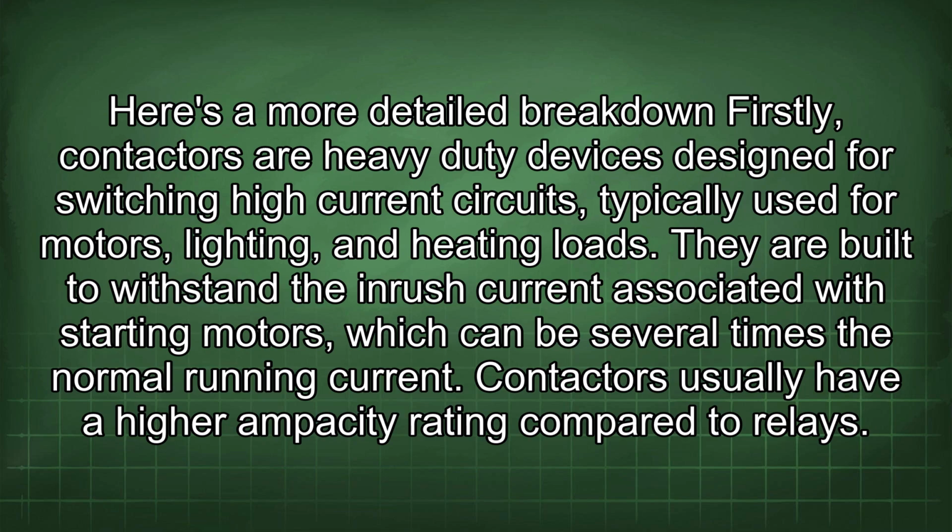Firstly, contactors are heavy-duty devices designed for switching high current circuits, typically used for motors, lighting, and heating loads. They are built to withstand the inrush current associated with starting motors, which can be several times the normal running current. Contactors usually have a higher ampacity rating compared to relays.